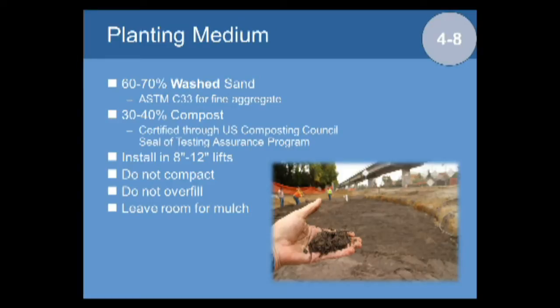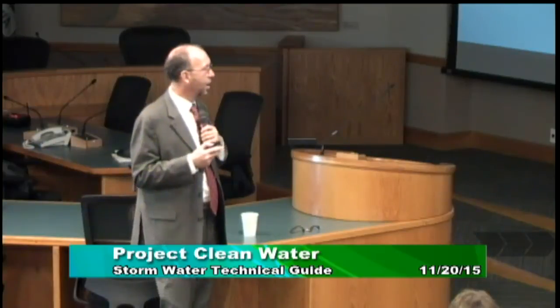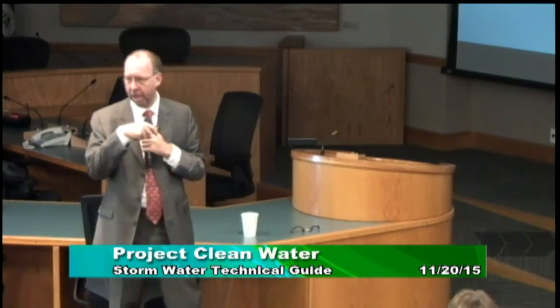Planting medium. I don't know whether folks are having any trouble getting this stuff now. What happened in the Bay Area is that the compost market has been turned on its side by the demand for bioretention, because there are so many facilities going in, that it's affected the cost and availability of compost. But the key thing here is this mix works to have this concentration of runoff going through it over and over again only when there's no clays in it. If you mix clay and sand, I don't know if we have any gardeners here, you put water on that a few times and it turns into the most amazingly impermeable material that you ever saw. And that's exactly what has happened when we've had clays contaminating the mix.